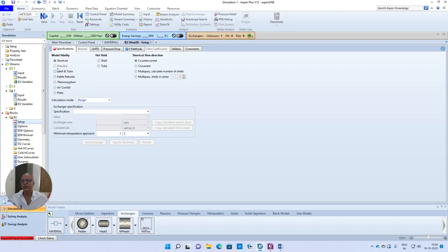So I have selected, for example, if you want to go into detail, this option is not available if you want to perform detailed design calculations within this model, right? Similarly, when you press air-cooled plate, some of these design options are not available within this model. Automatically, exchanger design and rating will be activated. So that can be done.